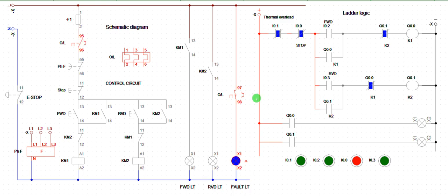This one is NC, this one is NO. Once this one opens, this one will close. Both of them change state, and this alarm will come up. Okay, until you reset the system, you are not able to start again. If you don't reset the system and you try starting again, you cannot start. None of them will operate until you reset the alarm.